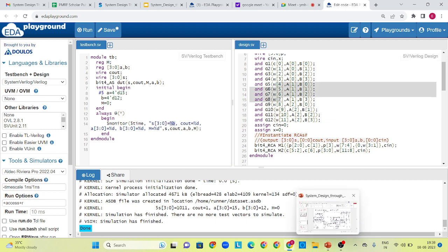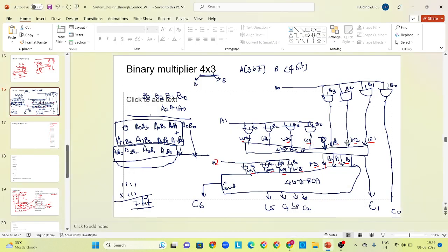Okay, so I will show you here. For this, I have to apply W1, W2, W3 and 0. So I will perform a concatenation operation. Inside the bracket, I will write W3 down to 1 and 0, comma 0, and I will apply W4 down to 7. The output I will obtain is P0 to 3, and the Cn will be 0.